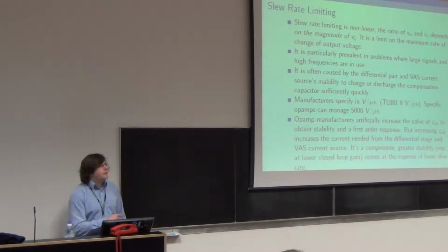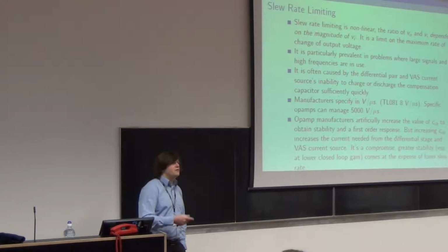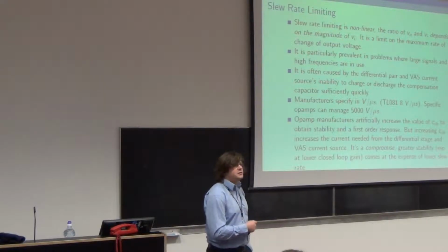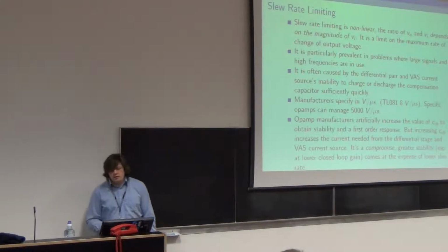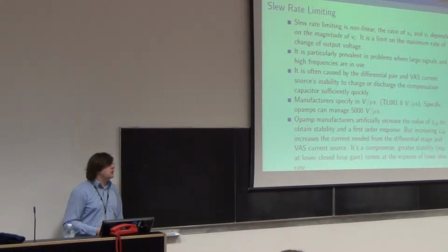So it depends on the magnitude of VI. You will see at smaller signals, you can get to higher frequencies without limiting. Bigger signals, you get limiting at lower frequencies. So high frequencies and large signals is what usually leads you into trouble.